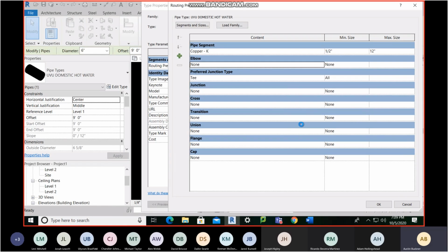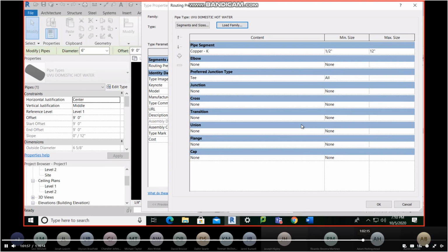Now, the reason we don't normally use generic is because in Revit, a generic fitting will look something like this. And Revit is going to show that as my 90 degree. If I plan on, let's say, a 2-inch offset, you can't create that. So you go out in the field and see two pipes at, let's say, 12 foot and 12 foot 2. In the BIM, you can't just make that with a generic 90 degree.